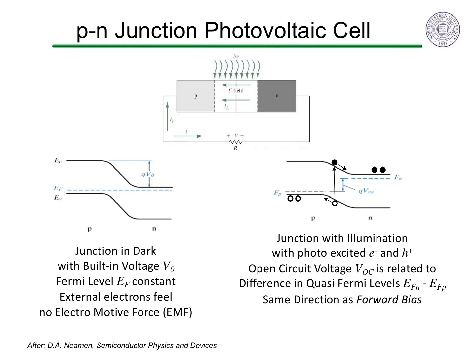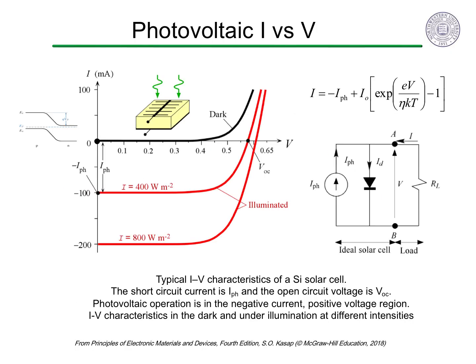During illumination, an external voltage would be sensed from a voltmeter indicating that an electromotive force has arisen, meaning the photodiode is acting like a battery supplying an electric current and voltage. The output voltage can be described by the difference in the quasi-Fermi levels. This diagram also gives a simple justification as to why the output voltage of a PV cell is limited by the band gap. If the output voltage times e is greater than the band gap, there will be no built-in voltage left. The photovoltaic IV characteristics can be understood as a combination of a diode and a current source.